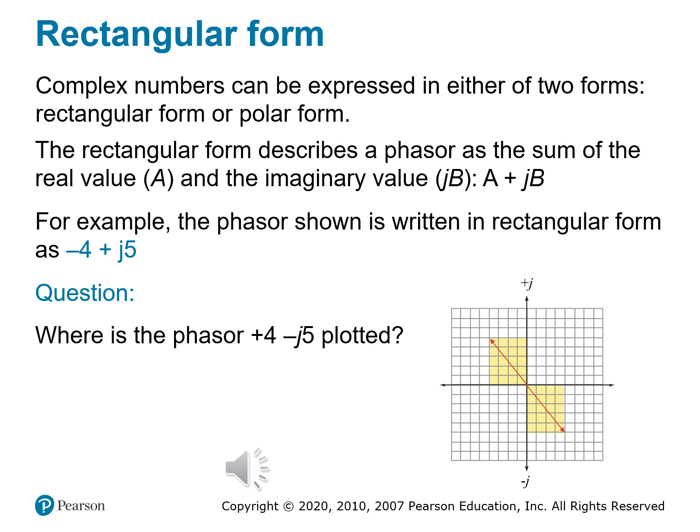I can't believe you're asking me that after you've taken algebra or trig or pre-cal, but let's go ahead and talk about it anyway. Rectangular form expresses a complex number or a phasor as a sum of two parts. So you have the real component along the horizontal axis, you have the imaginary component scaled by j along the vertical axis. And we write it in the following, where it's a plus jb.